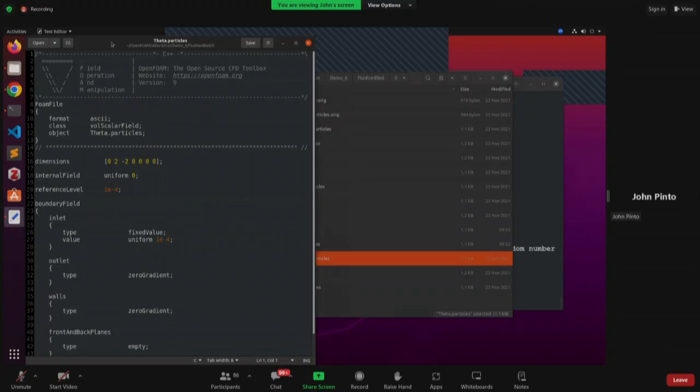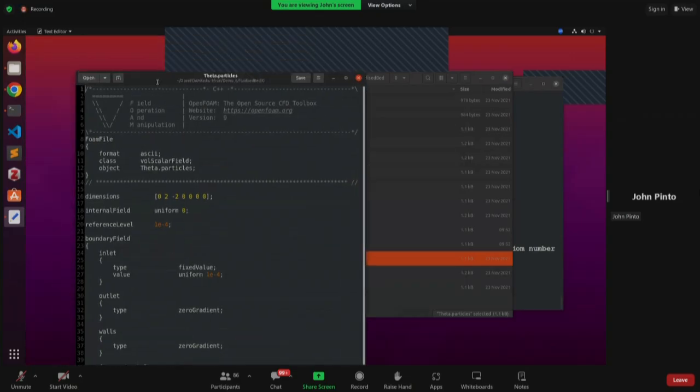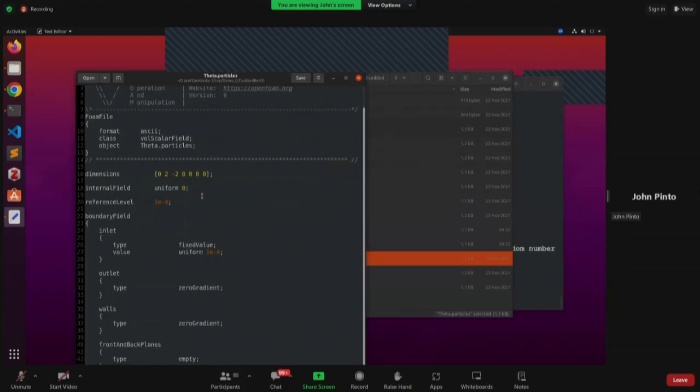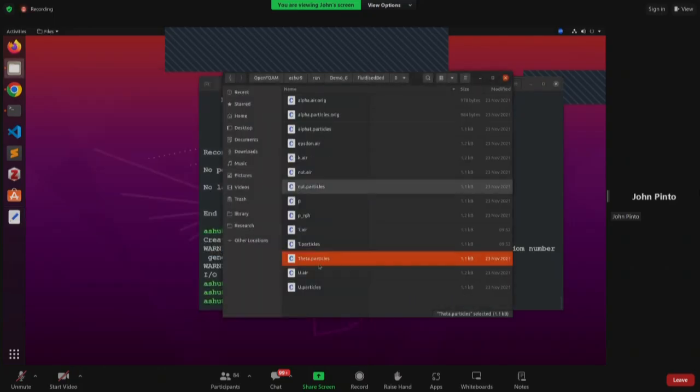Now this value is called the granular temperature. The granular temperature is something that will be calculated. We are just giving some initialization. Normally we generally initialize it uniformly 0 throughout, but some small reference values have been added because we want to avoid division by 0. So a very small value is being added to avoid division by 0.